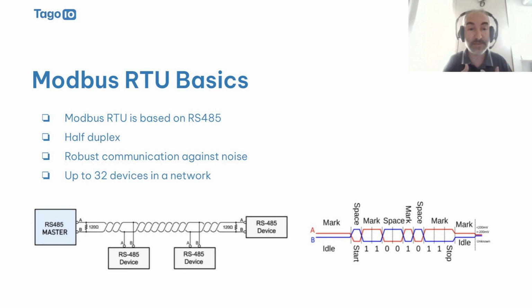There are some tips to implement to have the best Modbus communication from the devices. Termination resistor: since it's a differential signal, the lines must be terminated to avoid reflection on the line. Polarization resistor: since there are three states on the lines, the 0, the 1, and the high impedance state, when the lines are in high impedance, you need to keep them in a well-known status, so you have to add the polarization resistor.